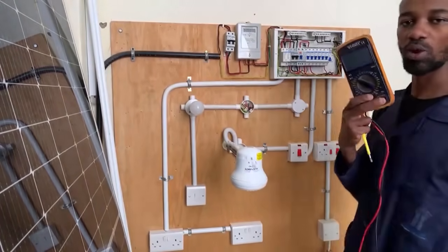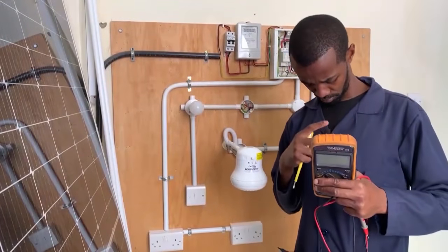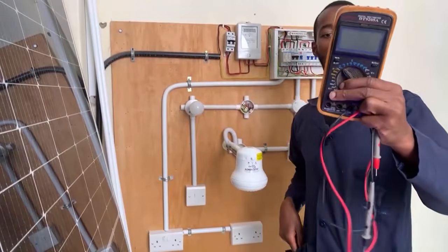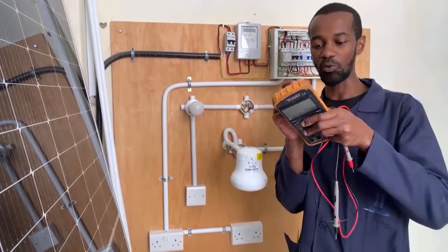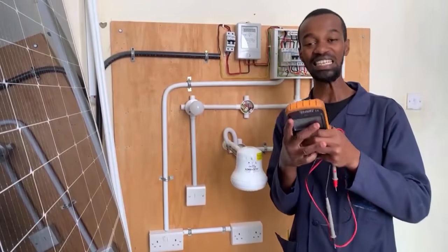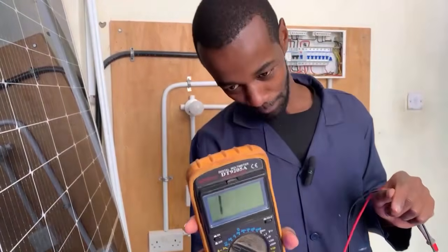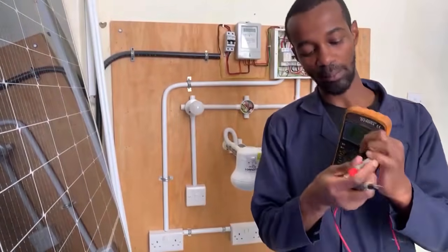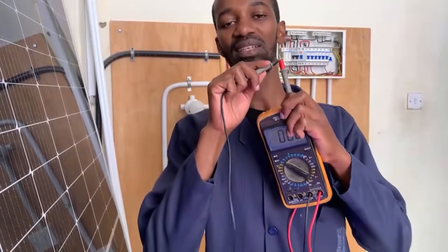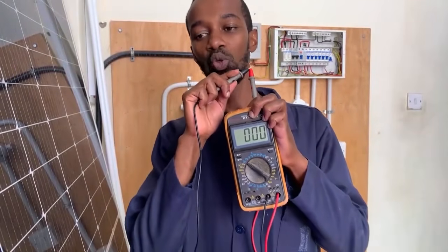Now, here is where this important instrument comes in, the multimeter. Digital multimeter. On our yesterday's live stream, we were able to talk much more regarding a digital multimeter. In fact, yesterday, we covered much to do with continuity tests. We agreed that a continuity test is whereby you bring these probes together and then you will hear that beeping sound, and it will shift from a 1 to 0.